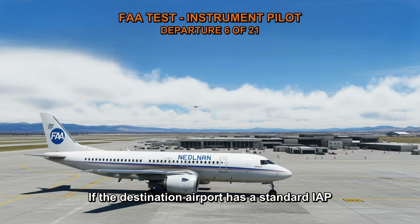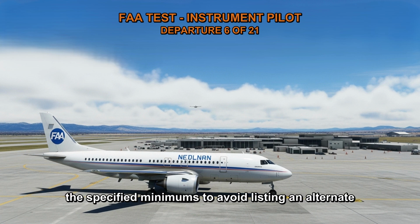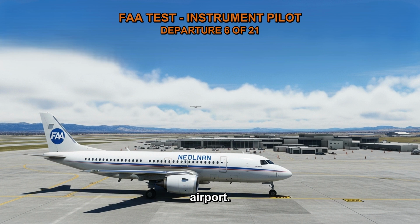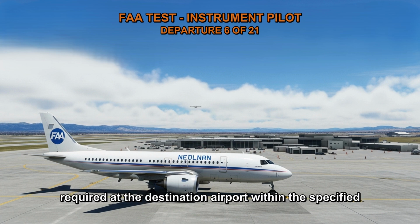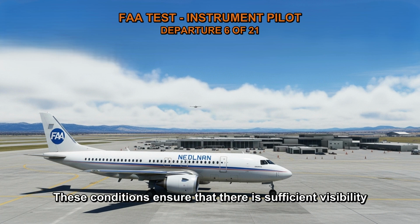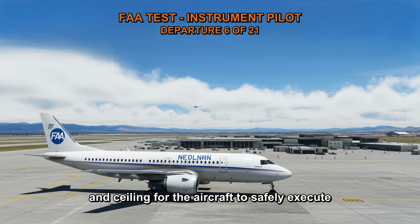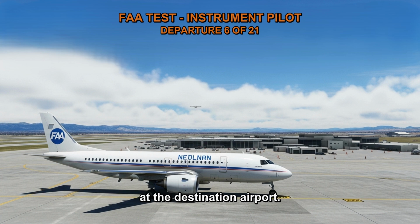If the destination airport has a standard IAP available, the weather conditions must meet or exceed the specified minimums to avoid listing an alternate airport. In this case, the minimum forecasted weather conditions required at the destination airport within the specified time frame are a ceiling of 2,000 feet and visibility of 3 miles. These conditions ensure that there is sufficient visibility and ceiling for the aircraft to safely execute the instrument approach procedure and complete the landing at the destination airport.